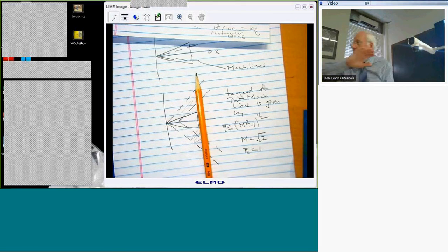Of course, behind the trailing edge, the flow is disturbed, right? But because of supersonic flow, any disturbance that occurs behind the wing propagates in the fluid forward at the speed of sound, but that's slower than the wing is moving, so that disturbance behind the wing never catches up with the wing. So if I'm on a supersonic wing, within the framework of this theoretical model, I don't know anything about what's happening behind the wing.